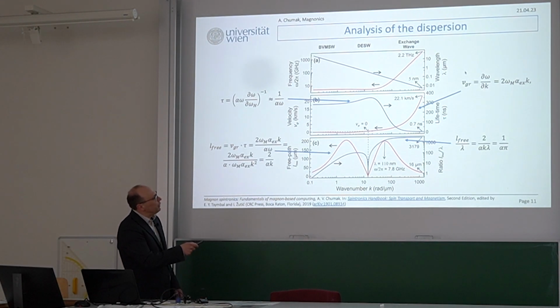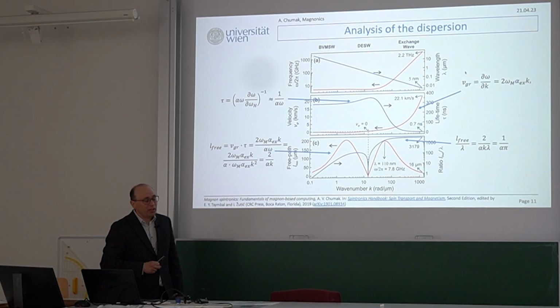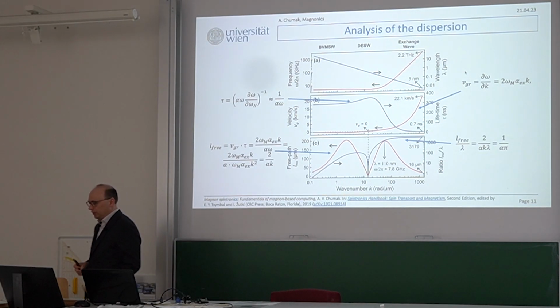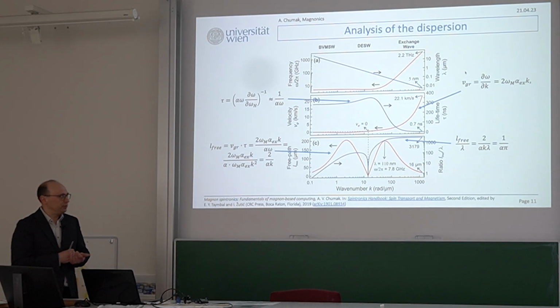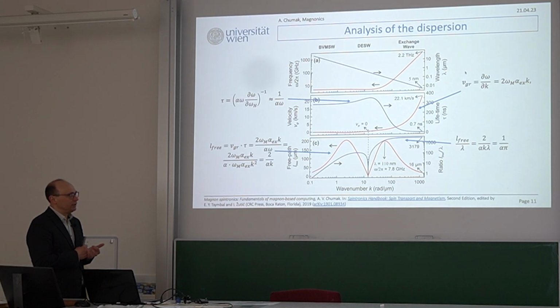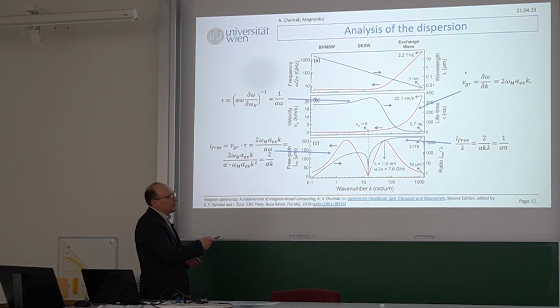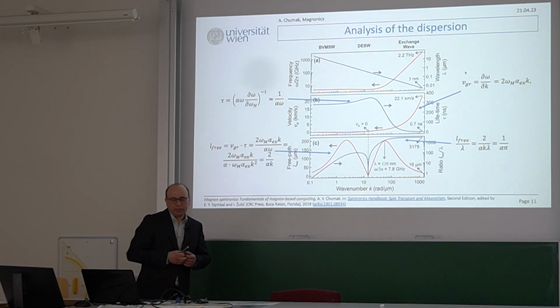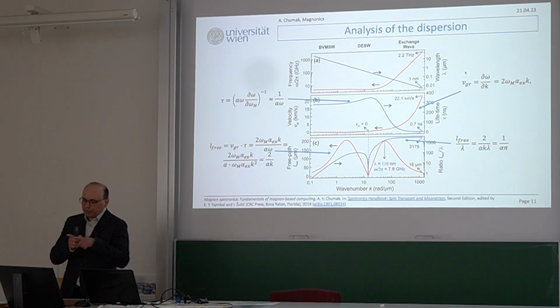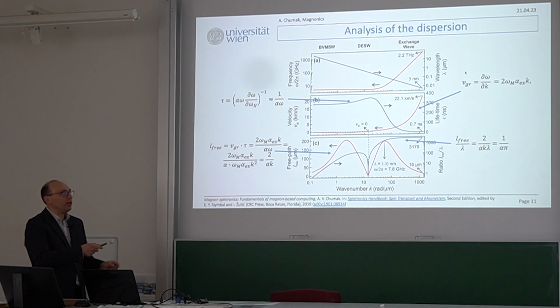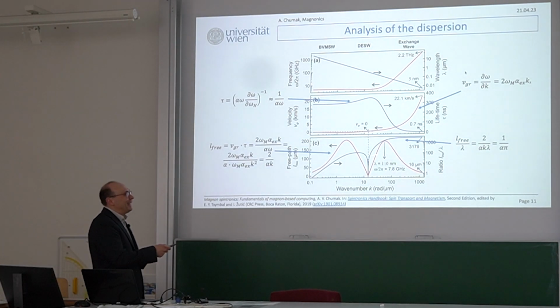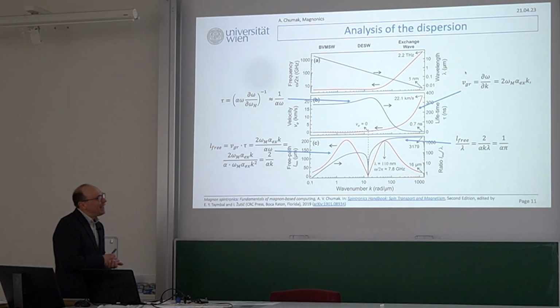And here the free path will be around 200 micrometers, which is a lot. It's more than enough for your structure. Usually your device is, I don't know, a few micrometers in length, so 10 microns. But principally, if you work with these wavelengths, then it's very good. This wavelength is possible to excite. You need to create a microstrip antenna, for example, to send current, and the width of your antenna should be smaller. Nowadays, we can do 50 nanometers. Again, Andrii can do that, and in Brno, in SciTech.